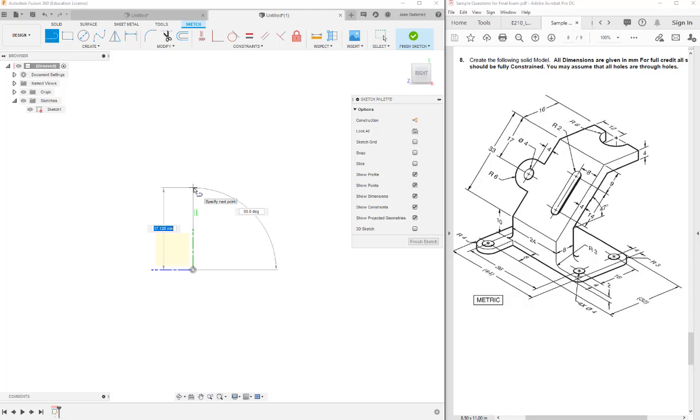And then before we proceed and do a rough sketch with the line tool, I'm going to make sure that that first dimension is fully constrained. So over here I see that that's 10. The reason I want to do that is that it's going to set everything to the right scale. If I make a rough sketch with the line tool and then dimension afterwards, everything could go out of whack, and then I could spend a lot of time redoing the work I've already done. I'm going to hide my sketch palette for now, but if I need it, I can pop it out over here.